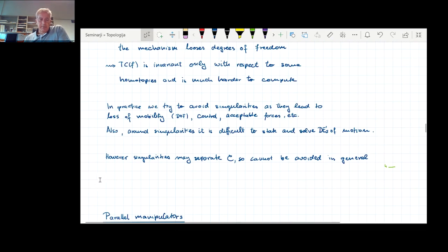But from the beginning, there was a question. This forward kinematic map is something that you can compute if you have a so-called serial machine. So you have a sequence of parts which are connected by joints, but they are kind of an open chain. This approach doesn't work very well if you have several chains which are connected.